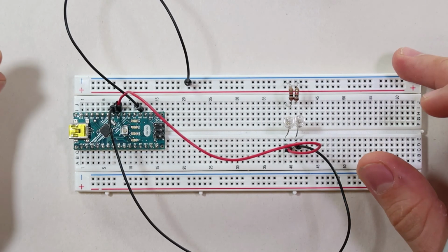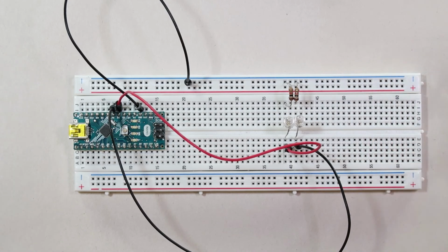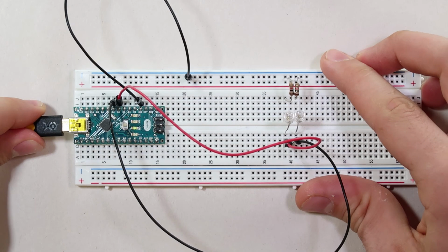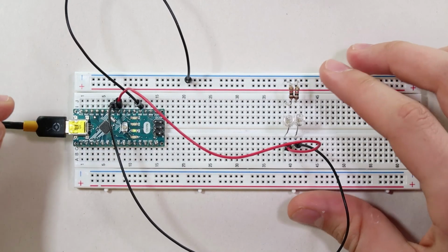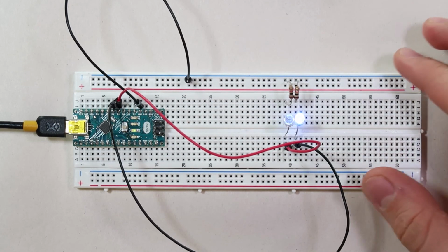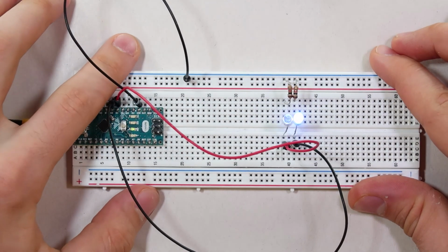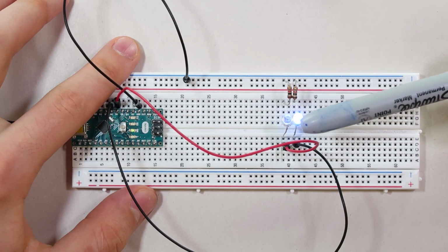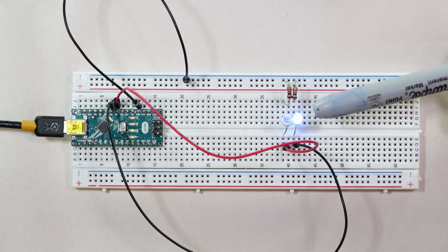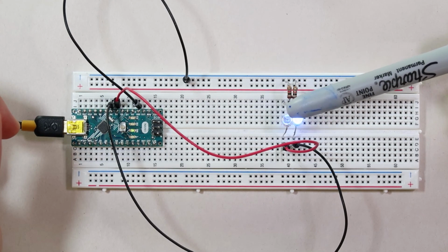Alright guys, so we're back with our first circuit, and we can now test our code and see if it works. We're going to plug in the Arduino to our laptop and run our script. And if you've implemented your code correctly, this is what you should see. So as you can see, this LED right here is at full brightness. I think I set it to 100% duty cycle. And then the other one, you can see, is definitely not as bright.